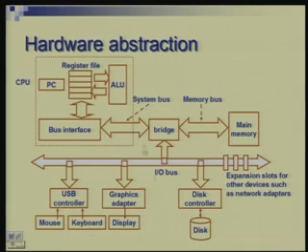They are connected to the system through a bus and some controllers. The processor is connected to memory again through some buses. This is a system bus, this is a memory bus, there is a bridge connecting these. Now, if you go further into this box which I have labeled as CPU, you will find that it is further subdivided. So, you have a program counter, register file, ALU and bus interface.